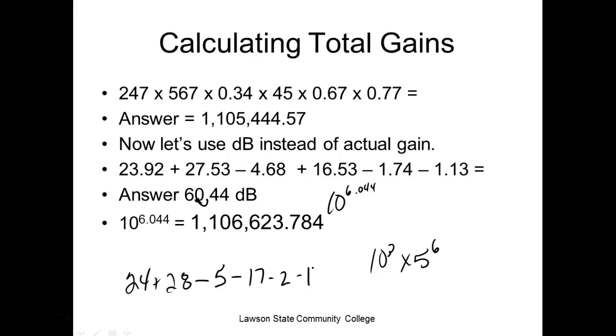You understand? So when we get into communications like wires and stuff like that, they're going to give us a 2-digit or single-digit dB. And of course, odds are it's rounded, but it's going to be close enough so I can tell if I'm expecting a 3 dB loss and I get a 15 dB loss, right? You know we got problems. If I'm expecting a 3 dB loss and I'm getting a 2.4 dB, I say everything's okay, because these dBs are going to be rounded, right?